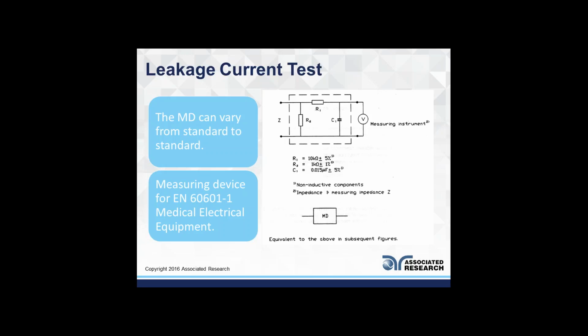Our instruments do carry the majority of the measuring devices listed in the standards, and we also have a space to design your own measuring device. If you had some requirements that are a little bit different than the standard measuring device requirement, you could actually make your own network of resistors and capacitors, what we call an external MD, which is designable by you, and we could still use our testers to test those.